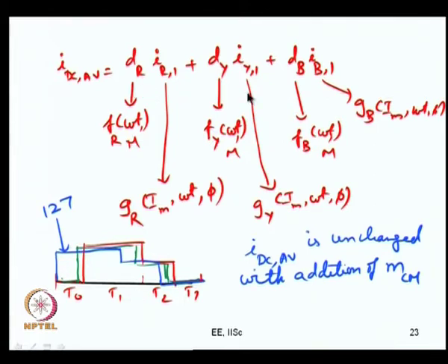So, this similar approach of duty ratios etc., we will be using when we go to evaluation of switching losses or conduction losses. In conduction losses particularly, you will have 3 phase currents, and corresponding to every phase current there will also be some amount of voltage drop, and the average voltage drop in a device would once again depend on the duty ratio. So, you will see there is some similarity there. We will do that in one module later; in the next module we will be doing the torque ripple analysis, and the module after that we will do this, but this kind of analysis will also be helpful now.